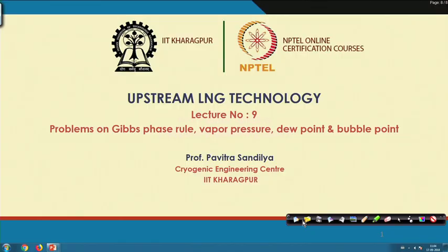Welcome. Today I shall be giving some corrections to my lecture number 9, in which I did some tutorial problems on Gibbs phase rule, vapor pressure calculation and dew point and bubble point calculation. In this particular tutorial you will find that some problems were done to use the Gibbs phase rule to determine the degrees of freedom, and then we estimated the vapor pressure, and lastly we solved a problem to find out the dew point and bubble point temperatures.